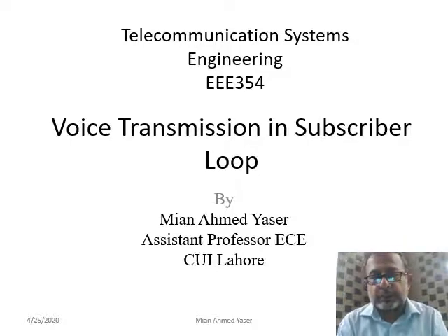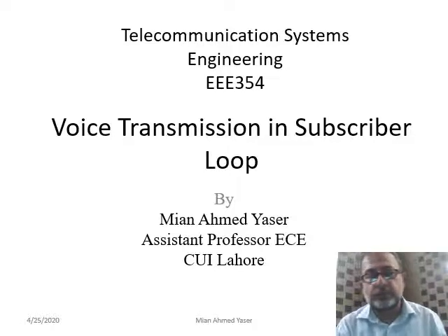All the telecom systems are basically based on the 0 to 4000 hertz band, and all the digitalization of this voice channel is done considering a voice channel from 0 to 4000 hertz only. We do not need to send the remaining 4000 to 20,000 hertz part.